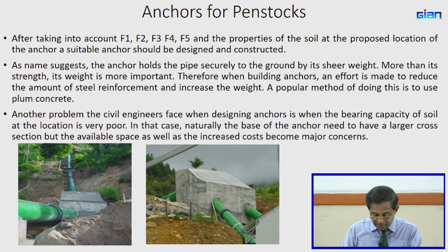and you can see here the expansion joint. This is the expansion joint. The expansion joint is always below an anchor, right, not on the upper side, otherwise it will tip down. Always at the upper end of the penstock between two anchors.